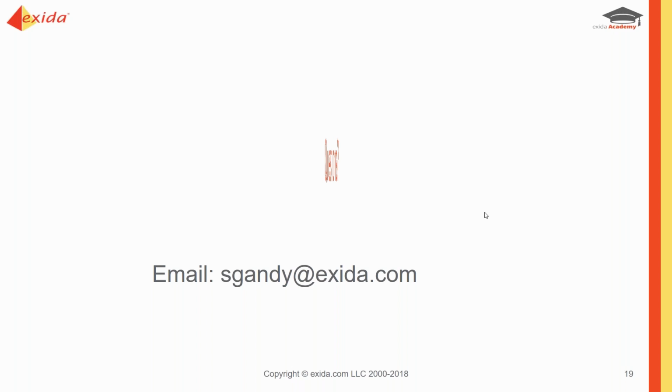We can generate that from doing a FMEDA, and that's usually what happens. That's part of the proven in use, of course. As we go through proven in use, depending upon the data that's available, you would use FMEDA to substantiate that. But if it's a certified device, the requirement is that the safety manual now has to include the useful life. And that's been in there since the 2010 1508 change. So manufacturers should by now have included useful life in safety manuals.